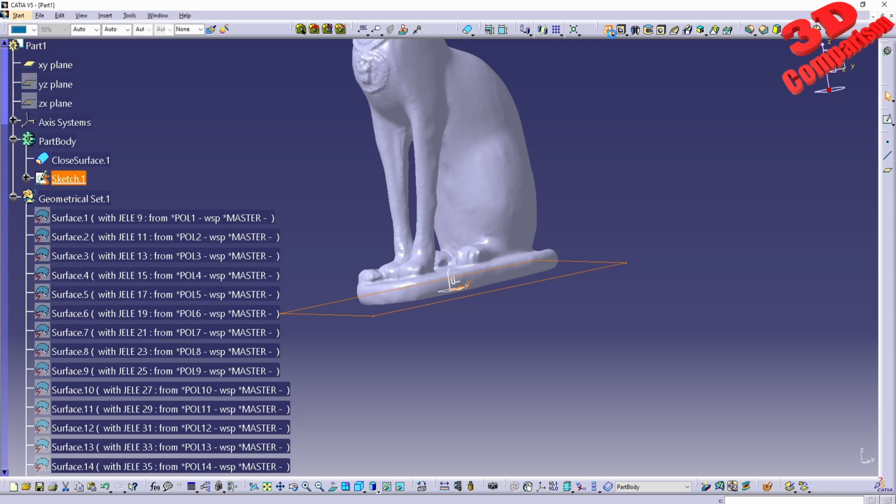But that doesn't mean it will not work. It will just take a little bit of time to process. Now, this will do an extrude, and since the extrude will automatically extrude upwards by default, it will also have a little bit of overlap with the existing geometry that is already a solid body, and this is why CATIA takes a little bit of time to process that.